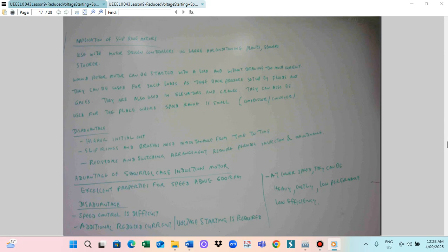So this is why we use the DC motor in the railway system, because in the railway system the train speed must be very adjustable. So you need to adjust it. A squirrel cage motor is not possible because you can't frequently adjust the speed. This is why we use the DC machine in the railway system. So the squirrel cage motors have good properties, but the speed regulation is the weakness, the minus for them.